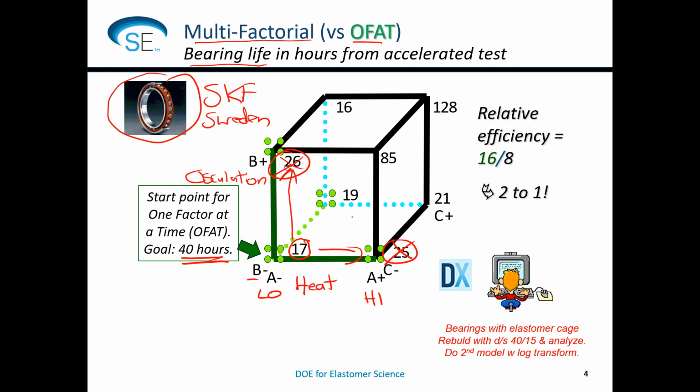So then the next thing they did was they went to the third factor, which is C, that's going from the front to the back, and they changed that one. That one was actually a categorical factor, and the original raceway of the bearing was metal. And actually you can see in the picture that they switched to a plastic raceway. However, just switching that metal to plastic made a very small difference. It certainly wasn't enough on its own.